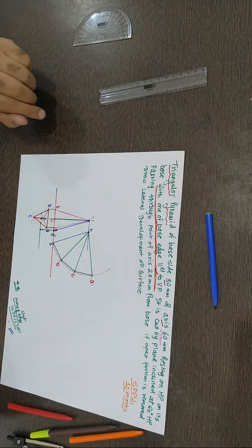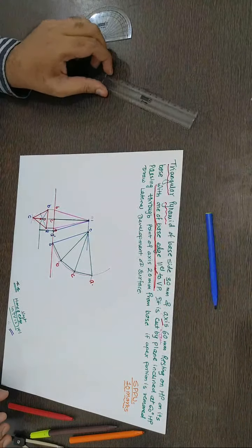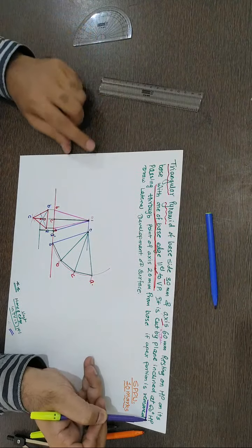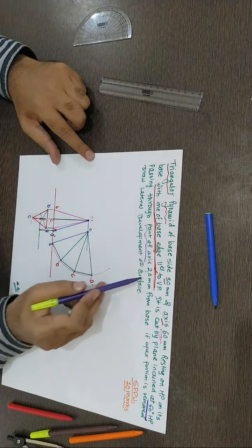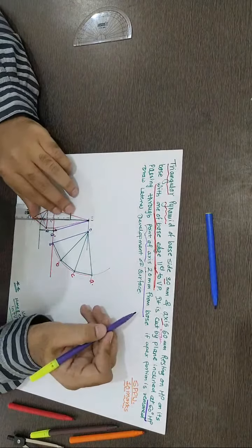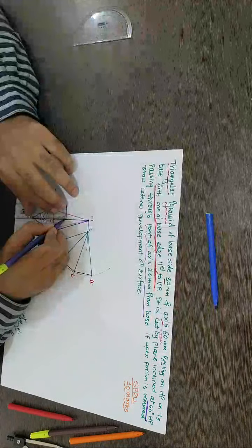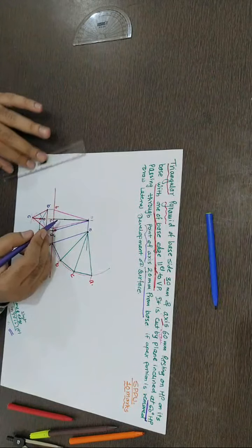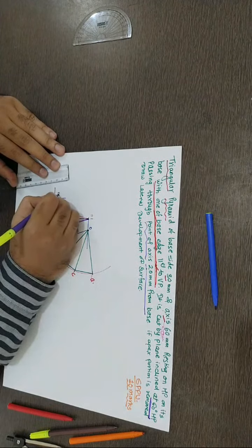Okay, fine. Now second part of this problem is intersection, means cutting plane. It is cut by a plane inclined at 60 degree to HP. So draw a cutting plane 60 degree to HP. It passing through the point of axis. So point, this is axis. Point of axis 20 mm from the base. So first locate the point which is 20 mm from base. So from 20 mm base is this point. So this is the 20 mm. I'll mark here. This distance is 20.